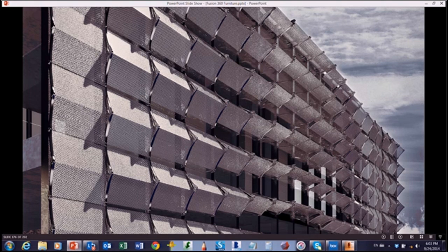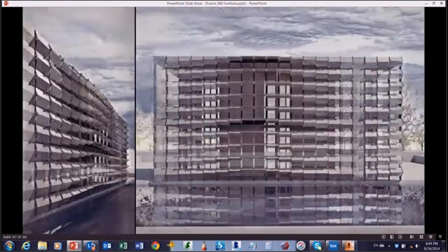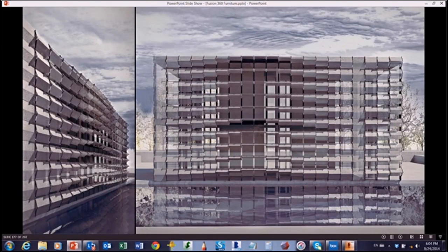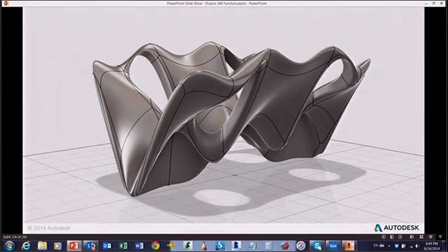A real quick trick on rendering, use cutout maps. I would never model that screen. You guys know how to use cutout maps? Those of you nodding your heads, everyone talk to the head nodders. You don't model that sort of detail in Revit. You use a cutout map. Find it in materials, play with it. Black and white images will create holes in your materials without modeling them. So if you're taking notes, cutout map in Revit, figure that out. It's an important one. Cool.